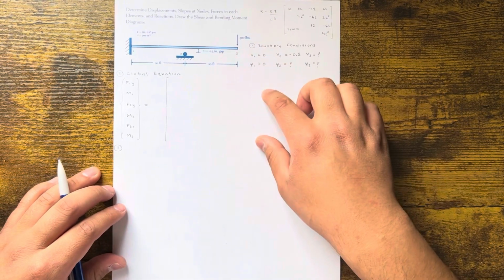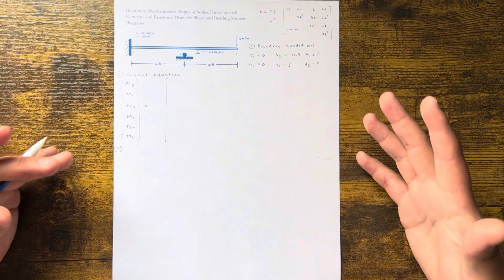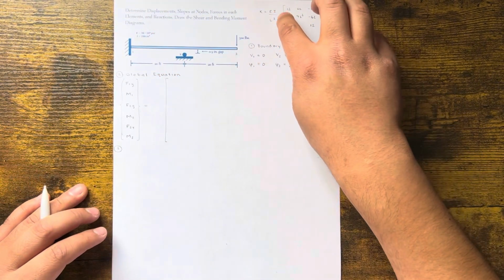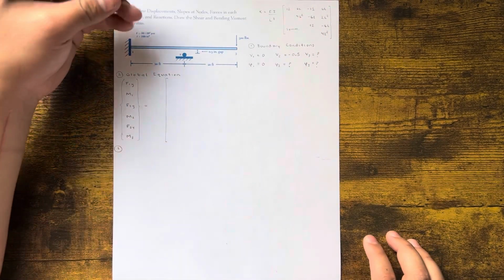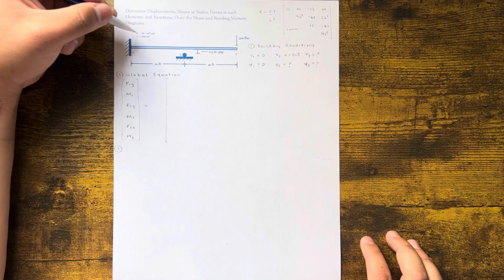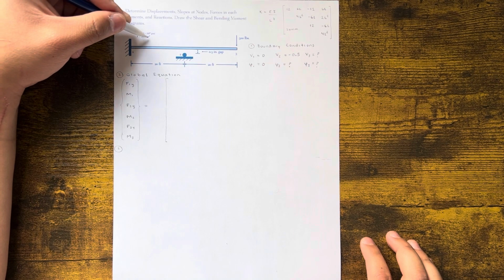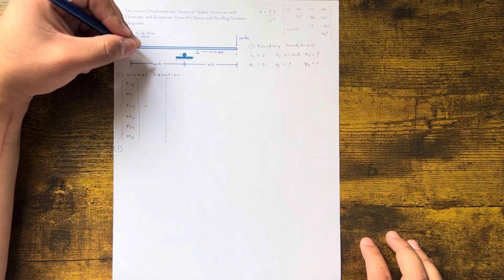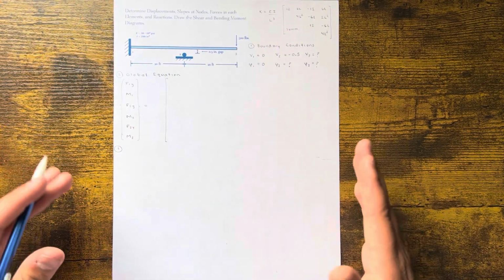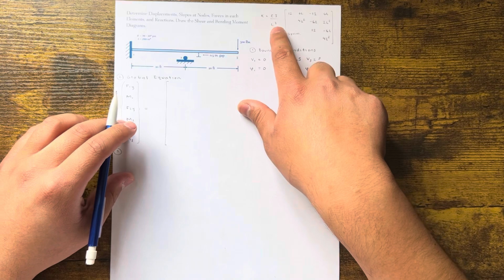And then we're just using the global stiffness matrix, so we have to incorporate every element. We need to know what EI over L cubed is. In this case, we're going to keep everything in inches, because E is given as 30 times 10 to the 6 psi and I is equal to 200 inches to the 4th. So we're going to convert these: 20 feet is 240 inches. Every element is 240 inches, and that's the number we're going to use for EI over L cubed.